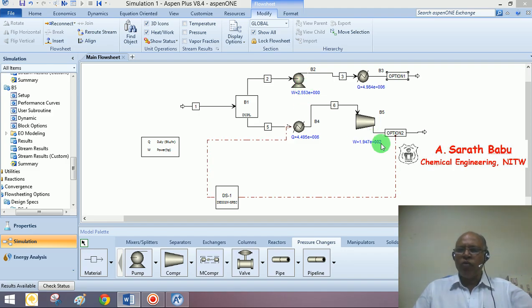Work is a superior form of energy compared to heat. So you are required to supply this much energy in the form of probably electricity for both pump and compressor. Now, how are you going to get your electricity? This being superior, you may have to convert some kind of heat energy into work, which will result in only 30% conversion.